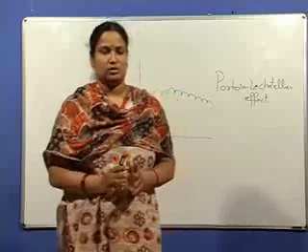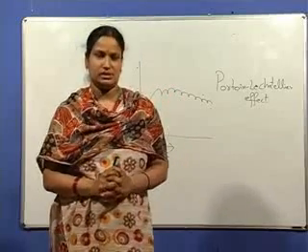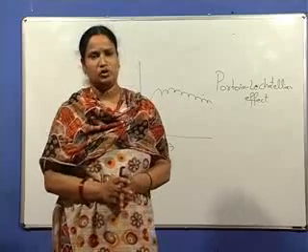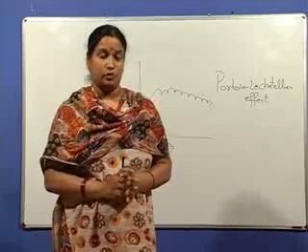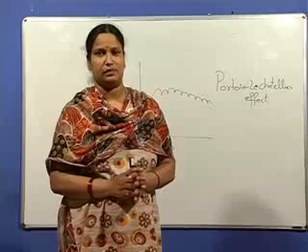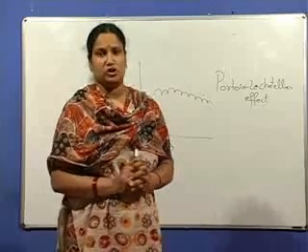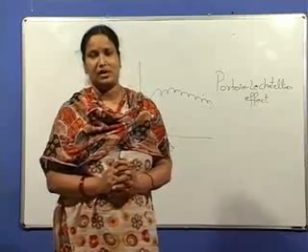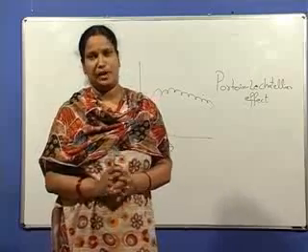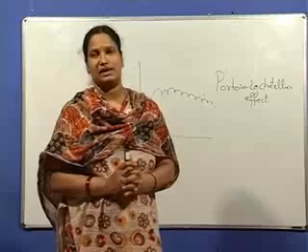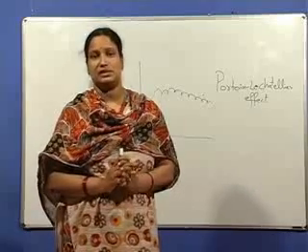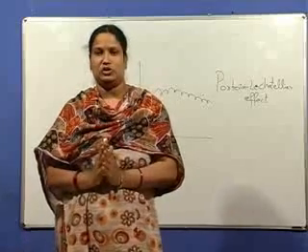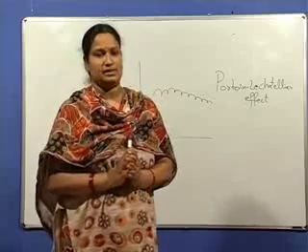So this is about the yield point phenomenon that occurs in low carbon steels, strain aging, two types, dynamic strain aging and static strain aging, and how to eliminate this strain aging and why it is required to eliminate it. All this has been discussed. And some portion of the plastic deformation in single crystals is left over, that is about the kink bands and deformation bands. The next will be the strengthening mechanisms, which is the main important part. So initially I will cover briefly the deformation bands and kink bands.